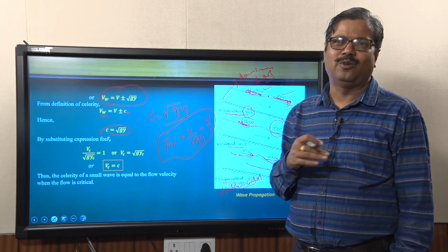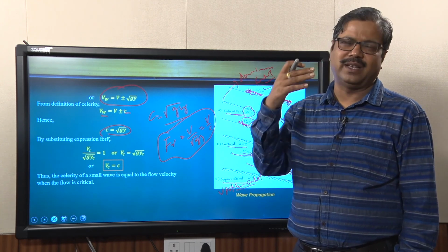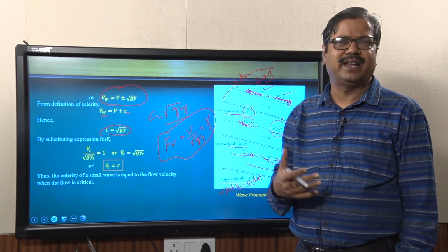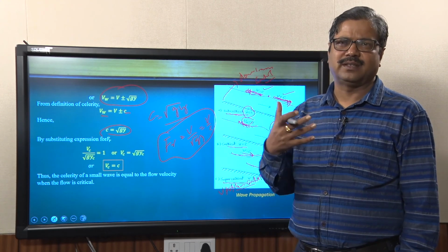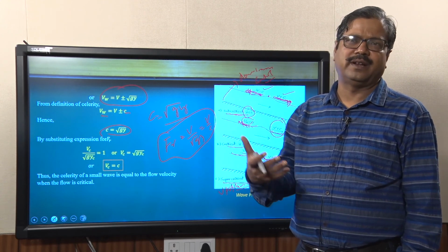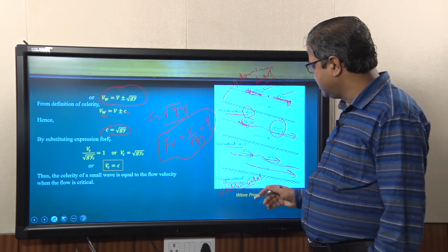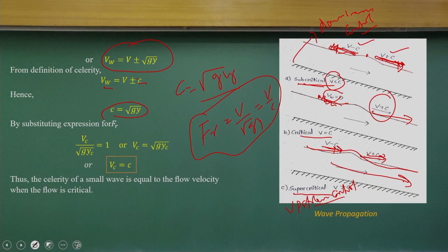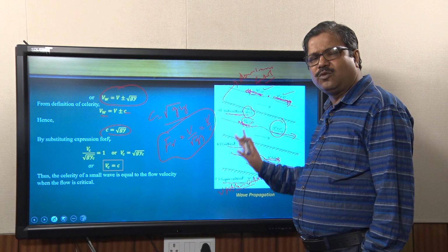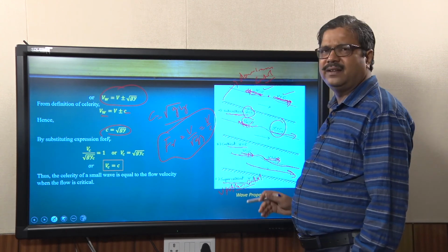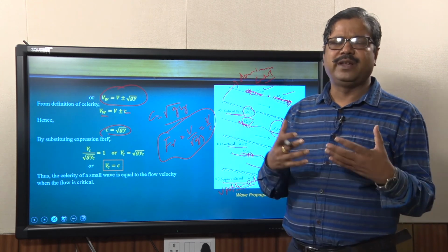So there is no laminar flow, and in some cases, like if there are sudden hydraulic drops, relief, or a gorge, there could be the formation of a hydraulic jump and supercritical flow. Those are conditions where it will be upstream controlled. The disturbance will propagate only in the downstream direction. So anything you control in the upstream is what will affect the flow. That's the way we define it, so in terms of flow behavior, we can understand it.